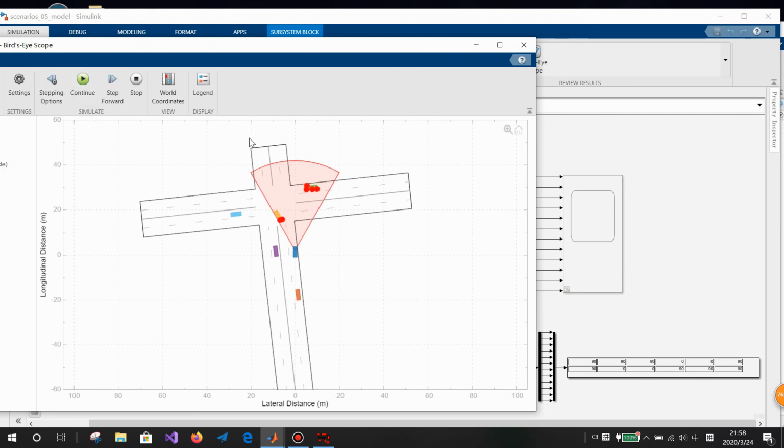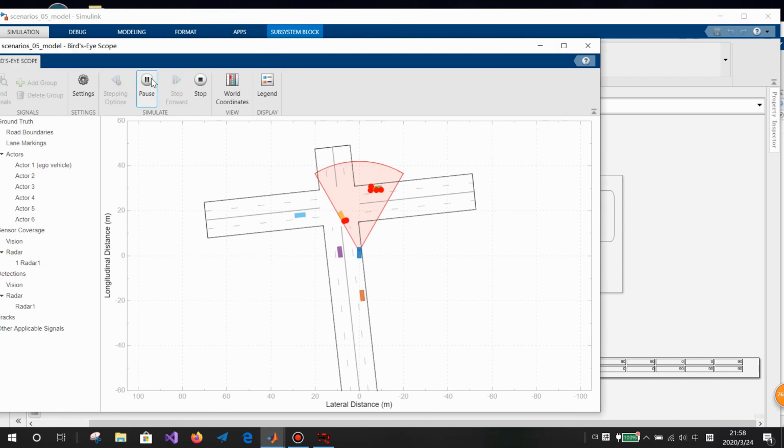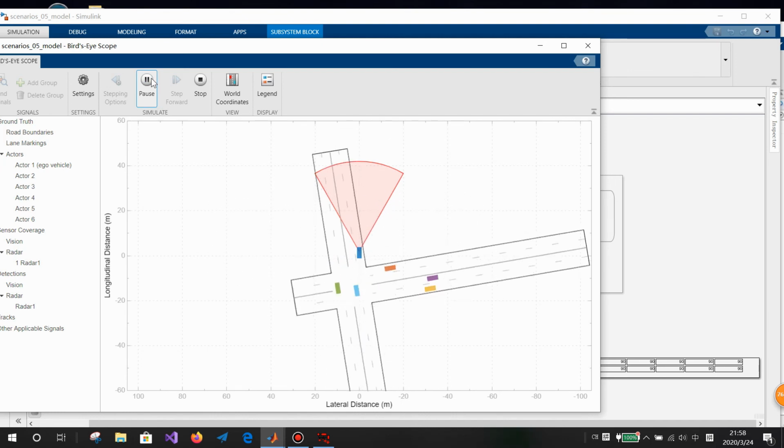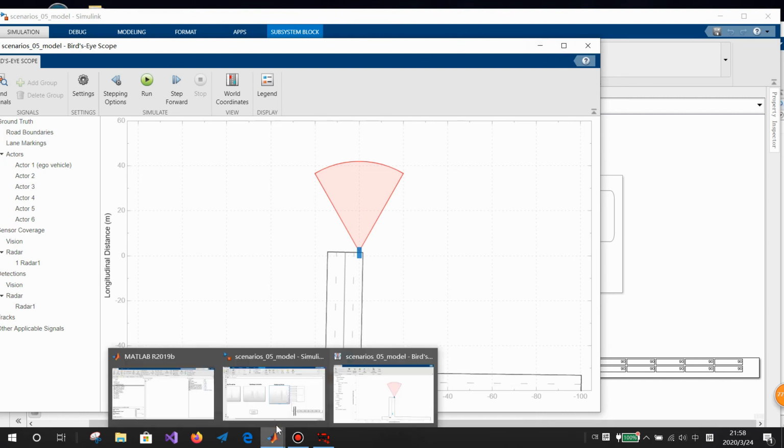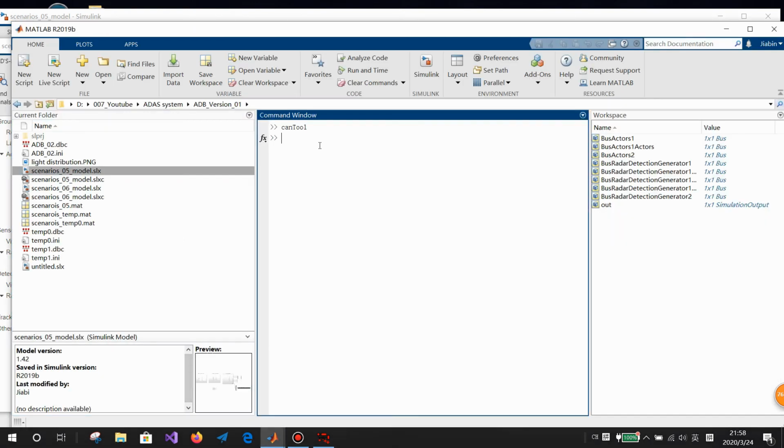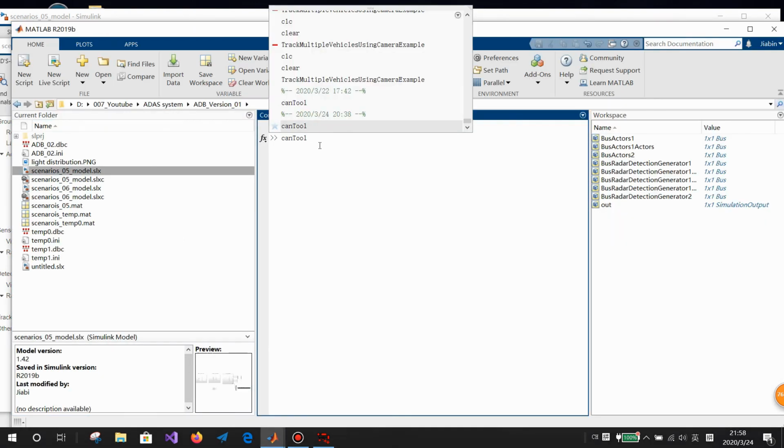And here we can see from the right side, the right up side, one LED shows off because there's a car here. See, this one's off. So basically it's working this way. So continue. And again, for diagnostic purposes, we can open the CAN tools again.